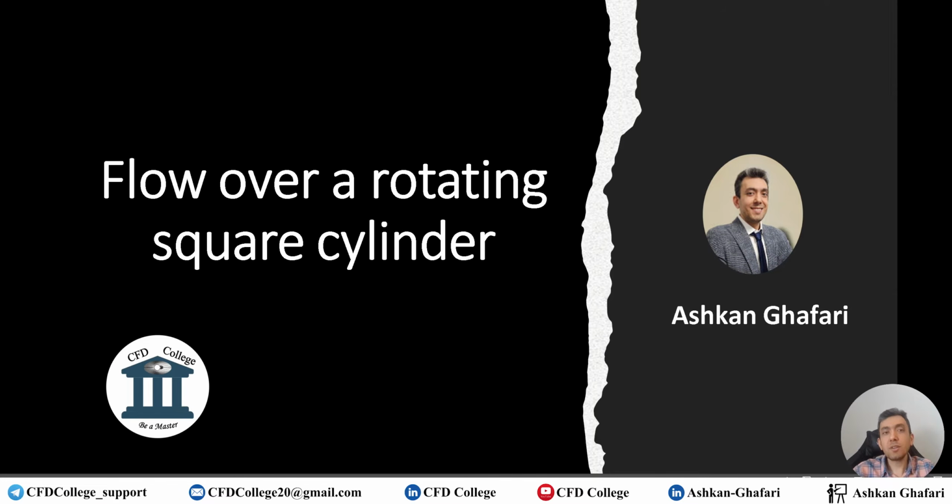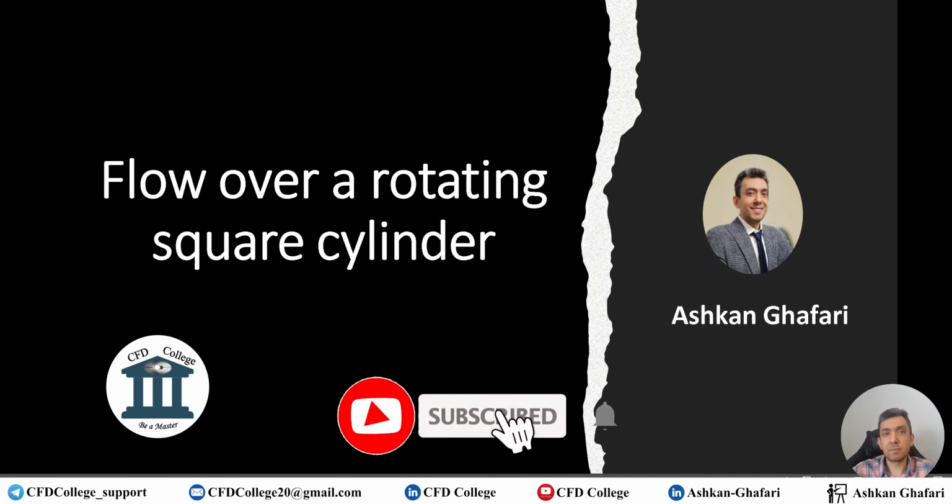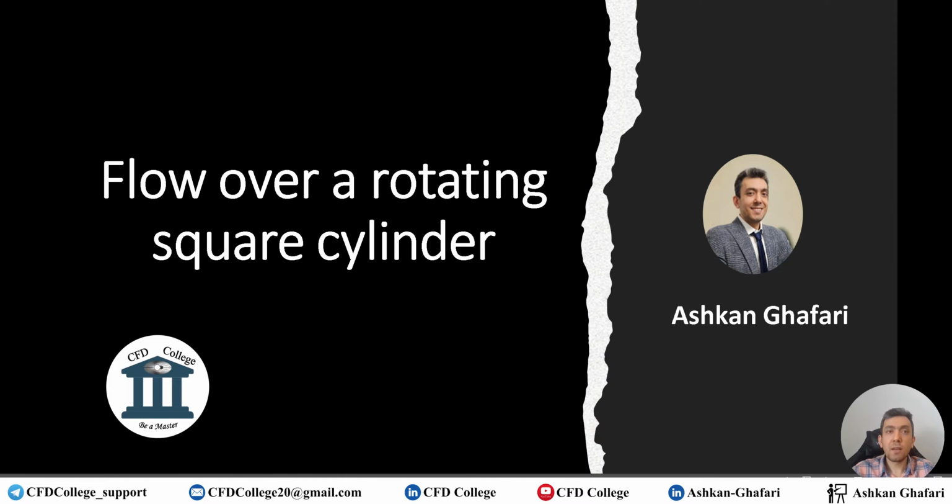But in this tutorial, the cylinder has a square cross section, so the procedure is totally different. In the previous tutorial, we used a boundary condition to apply the rotation, but here we should use free motion or mesh motion. I will teach you mesh motion today, which is known as sliding mesh.